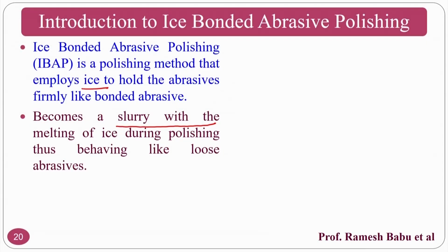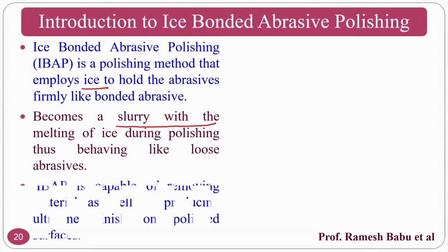Whenever it becomes a soft bonding, the debonding of abrasive particles will take place and new cutting edges will come. So the dressing is not required. Okay, maybe truing may be required if you make a wheel type of thing, but if you see the polishing pad or something in the upcoming slides, you may not require that also.